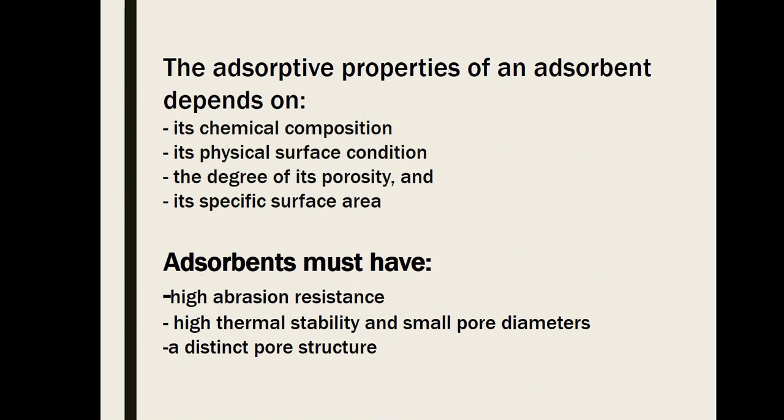Now, this is a requirement for all adsorbents: they must have high abrasion resistance, high thermal stability, and small pore diameters. Thermal stability meaning if there are changes in the temperature, their property to adsorb components on their surface should not be affected.